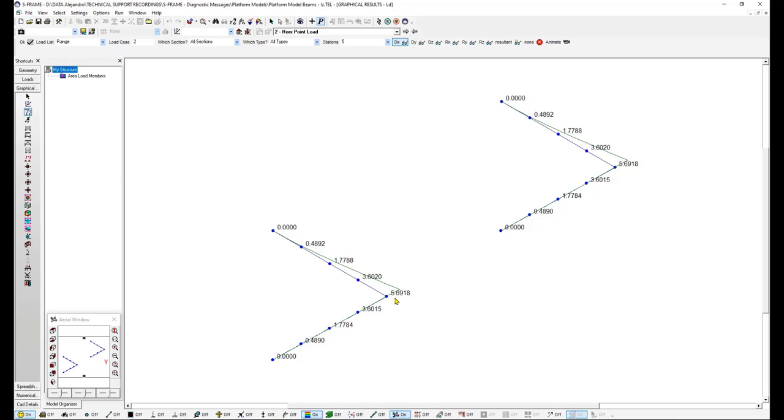So the lesson I would like to stress and that we learned today is we should always clean all solver diagnostic messages the first time we encounter them. Even if we are getting expected results, we should clean these messages the solver told me to fix 2 weeks ago when I defined the first load case. The other lesson is the sequence in which the messages appear. For example, you notice the instability message was the second message appearing, but when I addressed the first one, it got rid of this instability message. So we should always go and fix that first message.